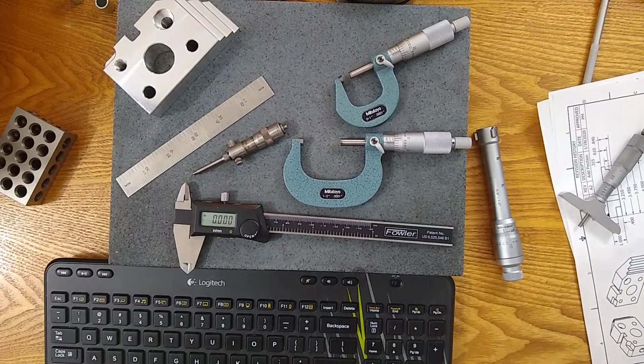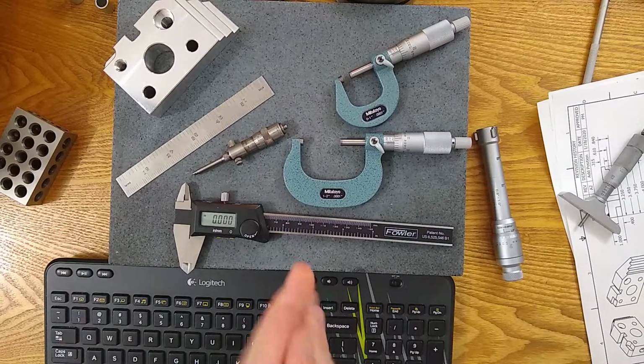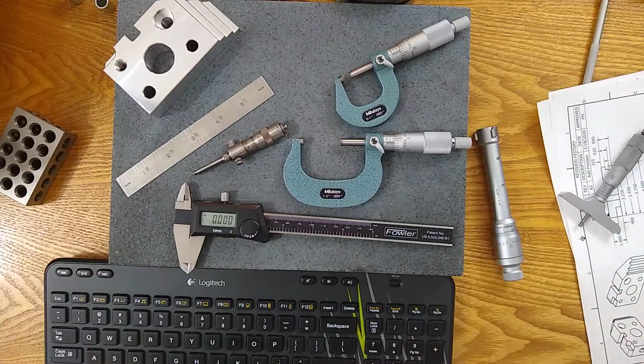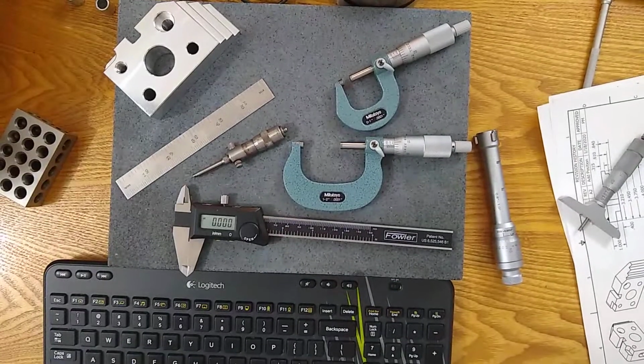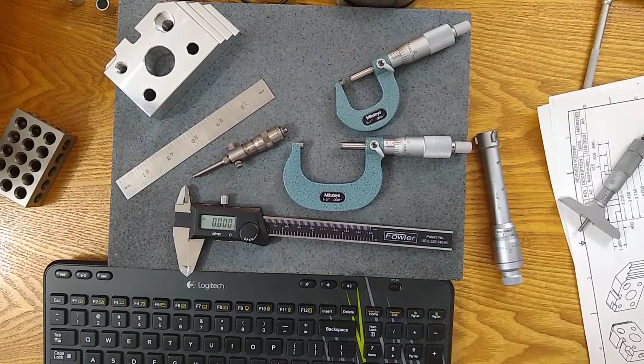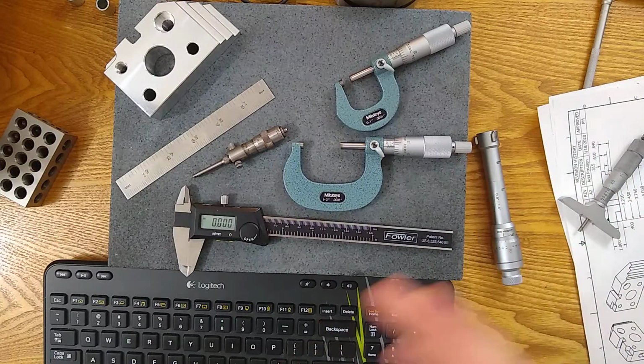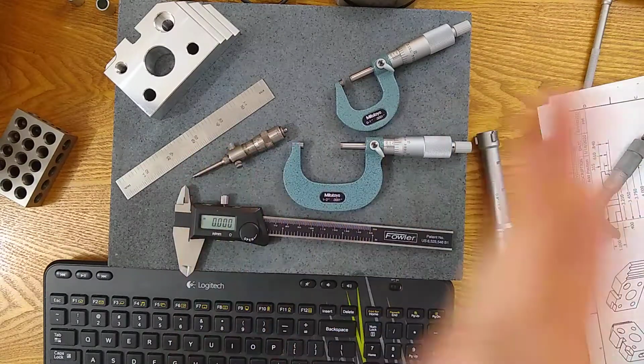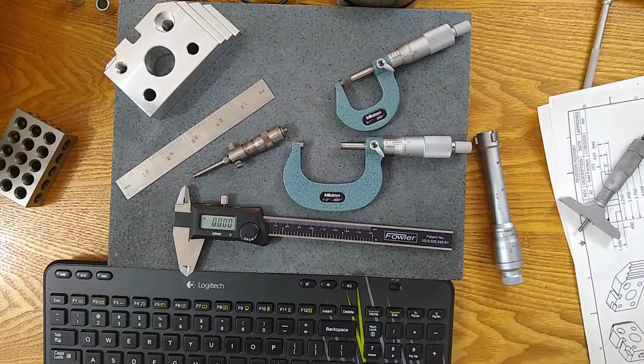So all requirements have a tolerance zone, right? No matter what you're inspecting, machine parts, plastic, sheet metal, whatever, you have a tolerance zone. All gauges have an accuracy uncertainty, that plus or minus from a nominal. And you ask yourself, what if your measurement is close to the min or the max of your tolerance zone? You have to calculate the difference. If I'm at the extreme of my gauge, am I outside of the tolerance zone?